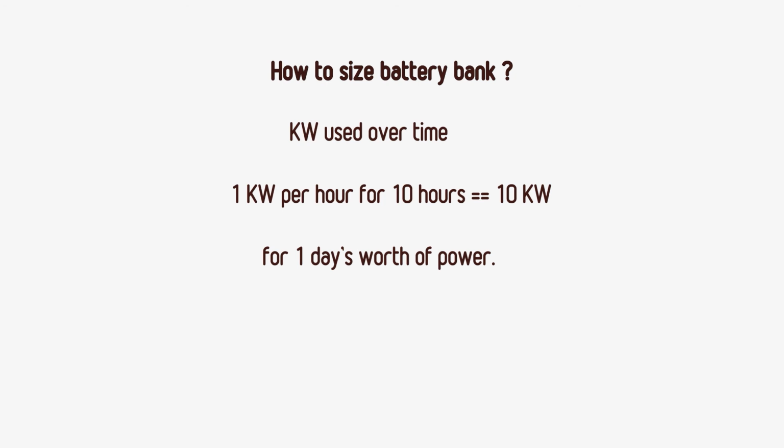So the calculation for how to size a battery bank really depends on your usage. What I did at my house is I got a Sense monitor and I plugged it into my circuit breaker just to see what my flow of electricity is throughout the day. I measured my total usage at my house.